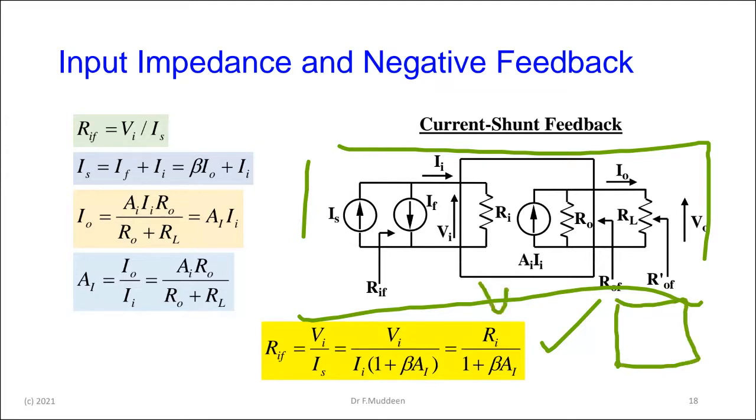That's voltage in and current out. So therefore the input is a Thevenin equivalent, right, which will be a source and a resistance, and the output will be a Norton, which is a current source and a parallel resistance. And then if you have that, to show me based on that what, for instance, current shunt feedback would look like, for argument's sake there.